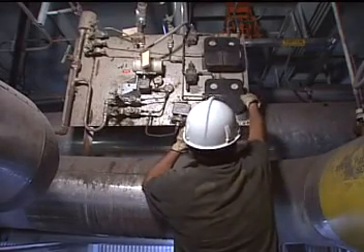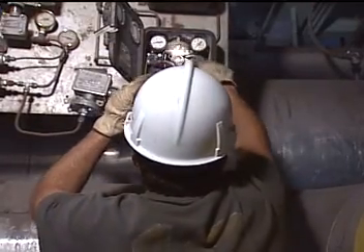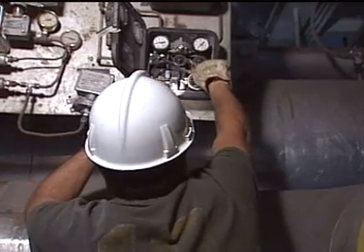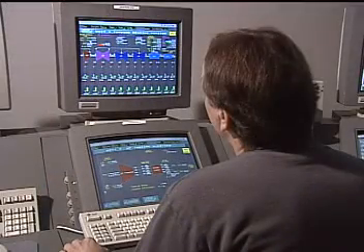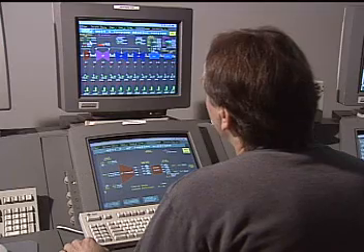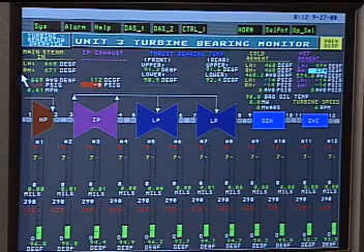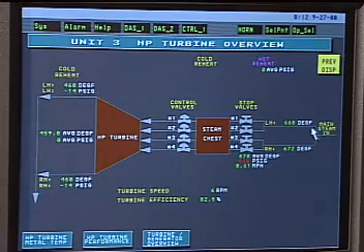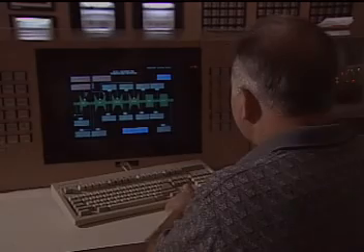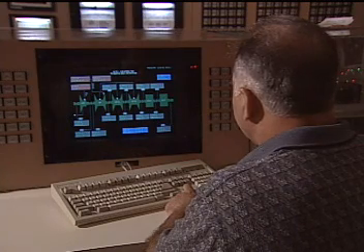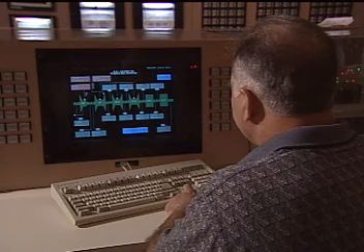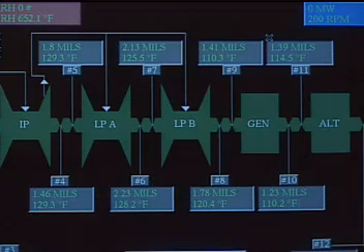Finally, during routine inspections, you should double-check that the valves on all the steam systems are correctly positioned or lined up. You should also monitor steam pressures and temperatures to make sure that the various steam systems in your plant are functioning properly. Different systems operate at different pressures and temperatures, so you have to know the normal operating temperature and pressure for each system.